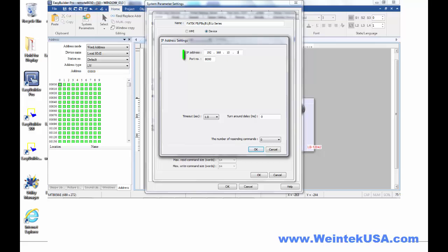So generally when you first select a driver, if it's HMI to device direct communications, it's a good idea to not change the port number unless you've got another good reason to do it. So this is where you set the actual PLC or device IP address.